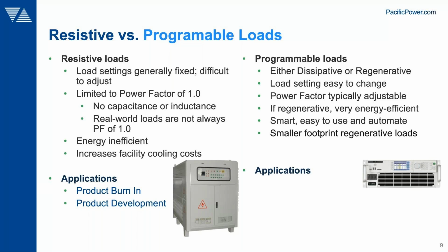Applications for programmable electronic loads are very similar to resistive loads in a lot of ways. They are often used for burn-in, and regenerative loads are especially suitable for burn-in because of the power efficiency that you obtain. For product development, of course, you have a wider range of capabilities on an electronic load, so you can program a much greater number of load conditions to really test out and shake out your power source designs.